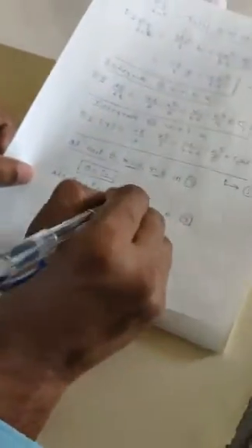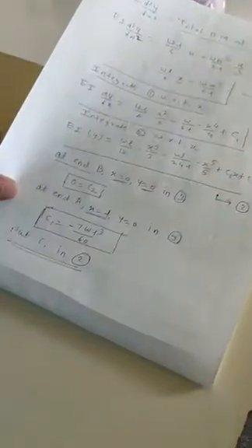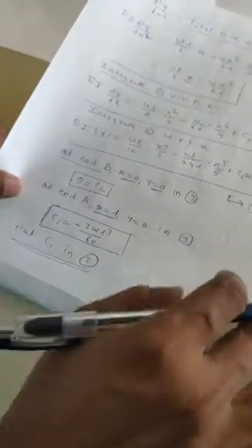Now to find the value of the other constant C1, we'll use the other known condition, that at A, x is L and y is equal to 0. Put it in the same expression number 3, and you will get the constant C1. Once we get the values of C1 and C2, we can find the expression for slope and deflection in numerical form.